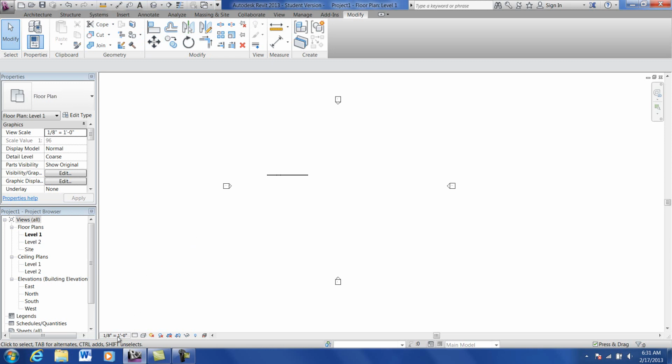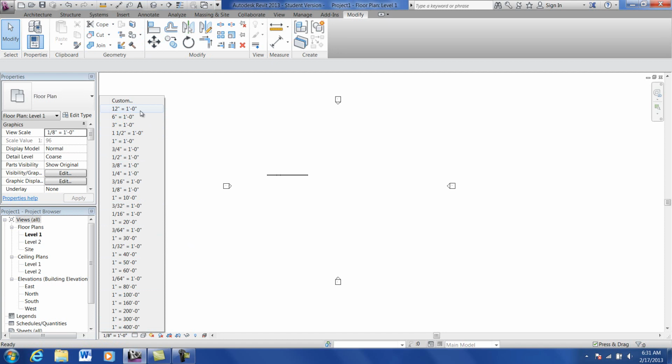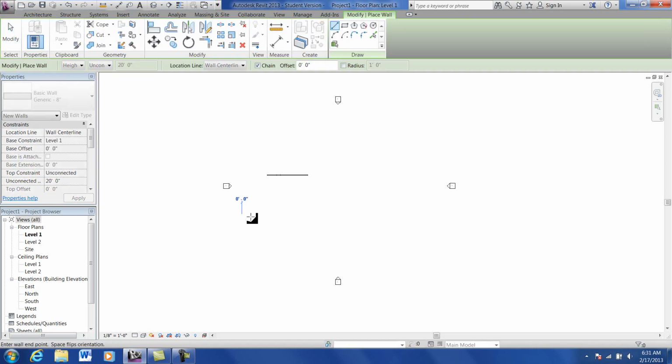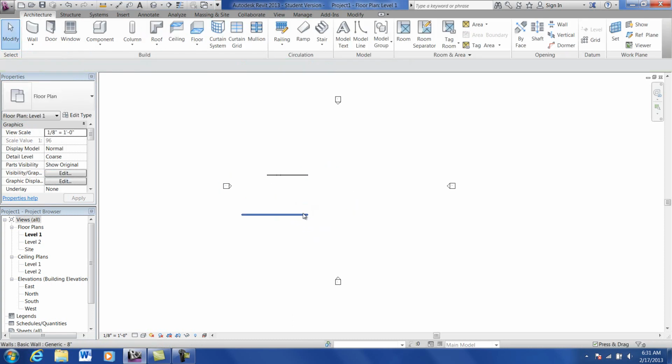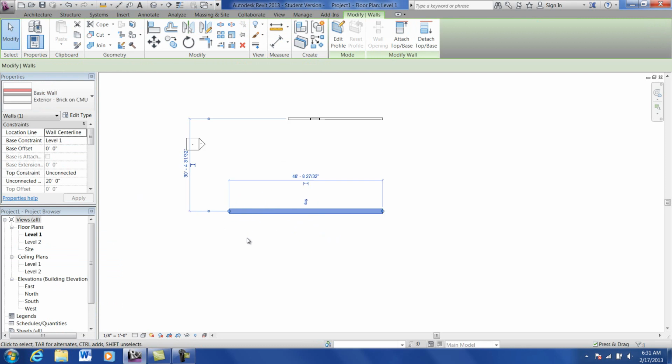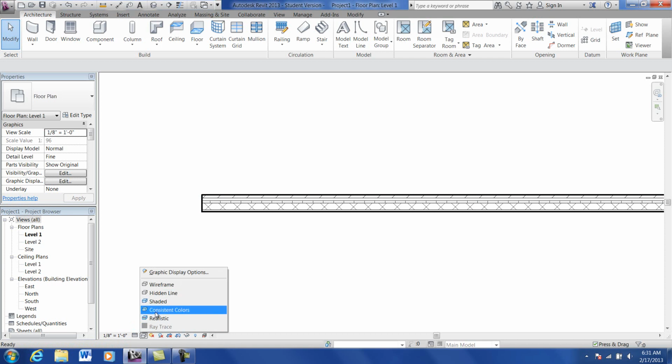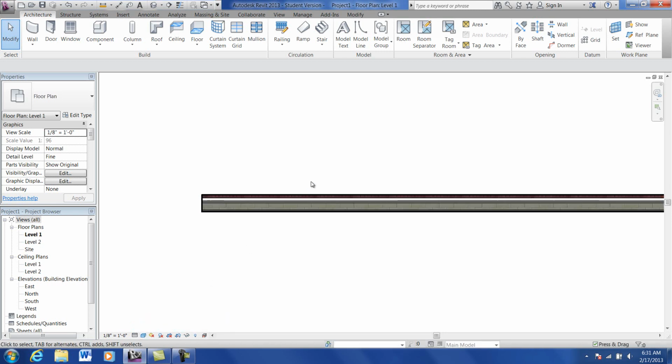And also, before I forget, at the bottom of your screen you can see the view scale, and next to it is visibility for 2D drawings. Means what? Means if I draw a wall like this type of wall, to be able to see all the hatches inside this wall or materials, I can select visibility, detailed visibility, and change it to fine. And next one is visibility with regards to consistent color, which is graphics material, and realistic, which is rendering materials in Revit.